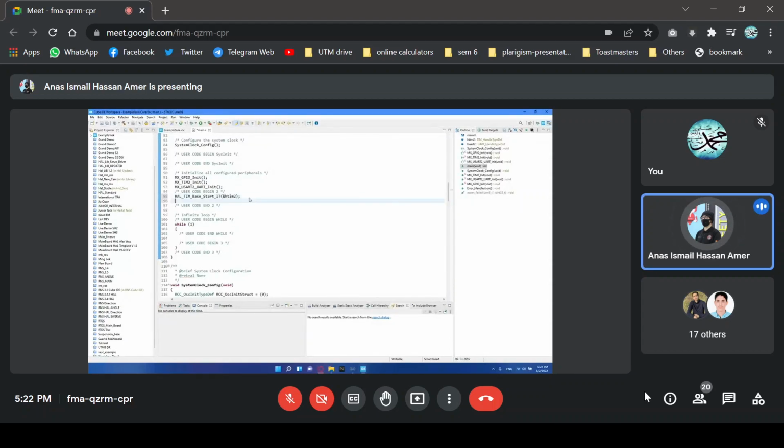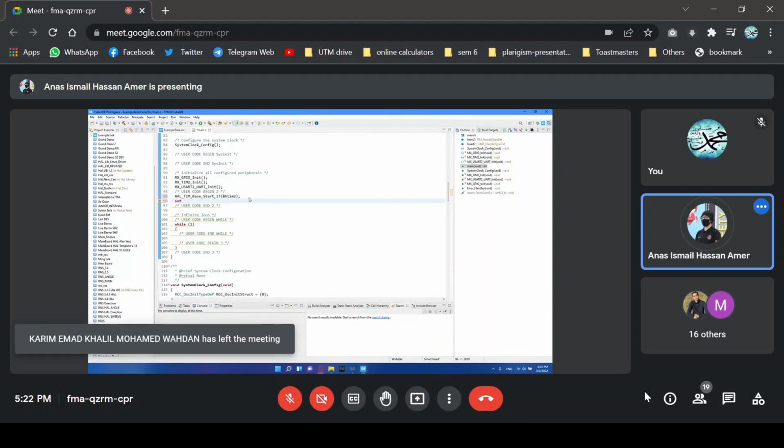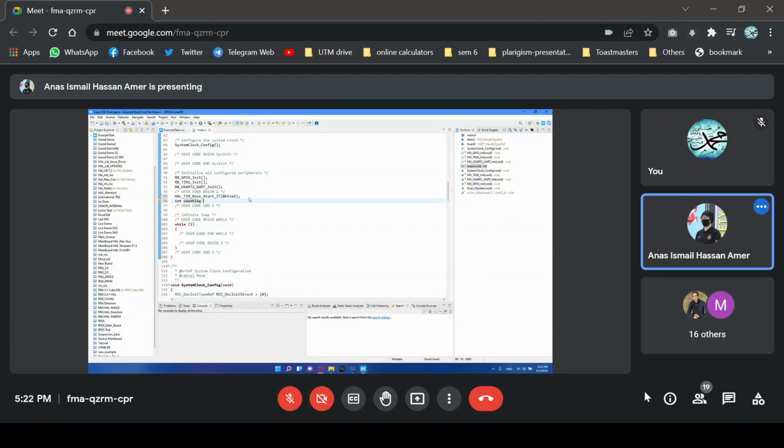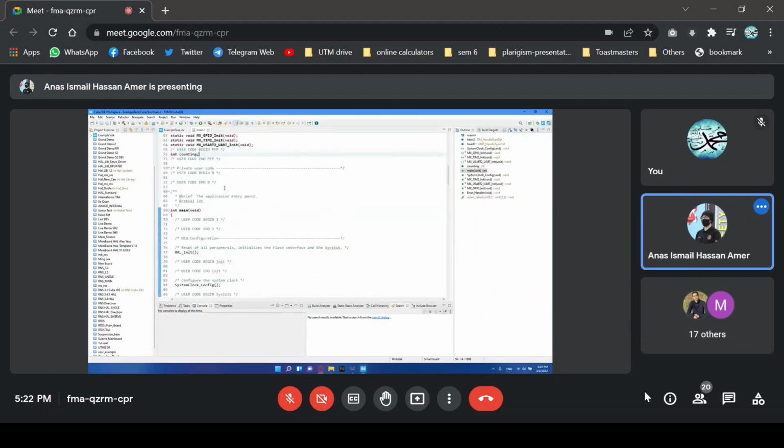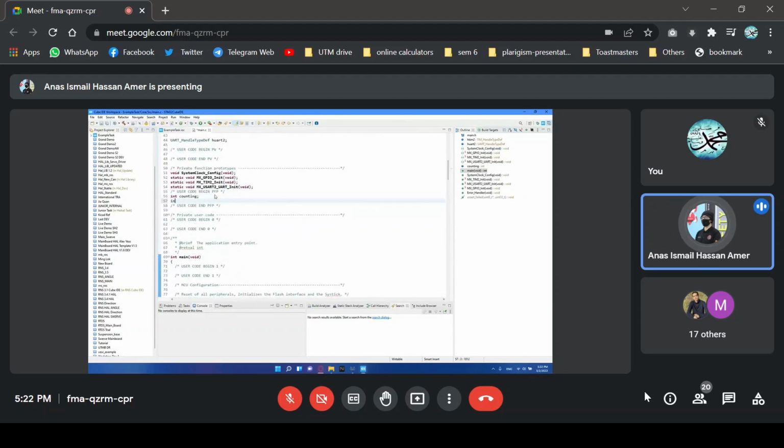Then let's add some variables. Let's add a variable to determine whether the timer should count or not. So let's say counting, equals 0. Then this also needs to be accessed inside the interrupt, so let's remove it from main and put it outside. Also add the time itself, but let's make it a float. So float time between the two sensors.